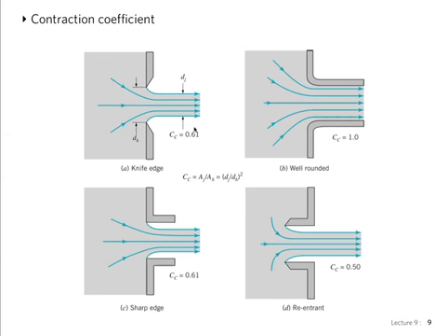Yes, we're not looking at surface tension effects here. Surface tension effects are completely neglected in this whole discussion. This is just the dynamic effect of the fluid not being able to turn the sharp corner and adapting, because it is now moving at speed. That's the situation of a jet.